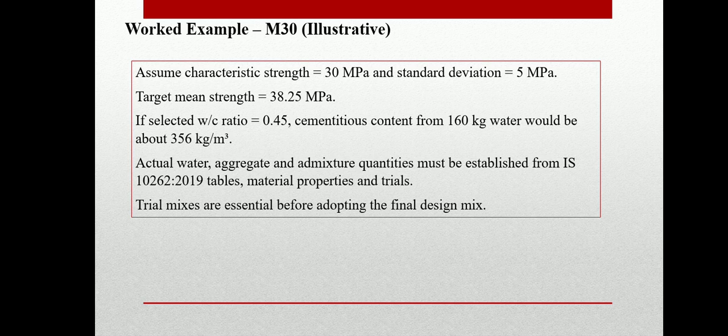This is purely illustrative. The actual water, aggregate and admixture quantities in a real design must be established from the IS 10262-2019 tables, the actual properties of our materials and confirmed through trials. So never treat a worked example like this as a shortcut to skip the proper procedure.